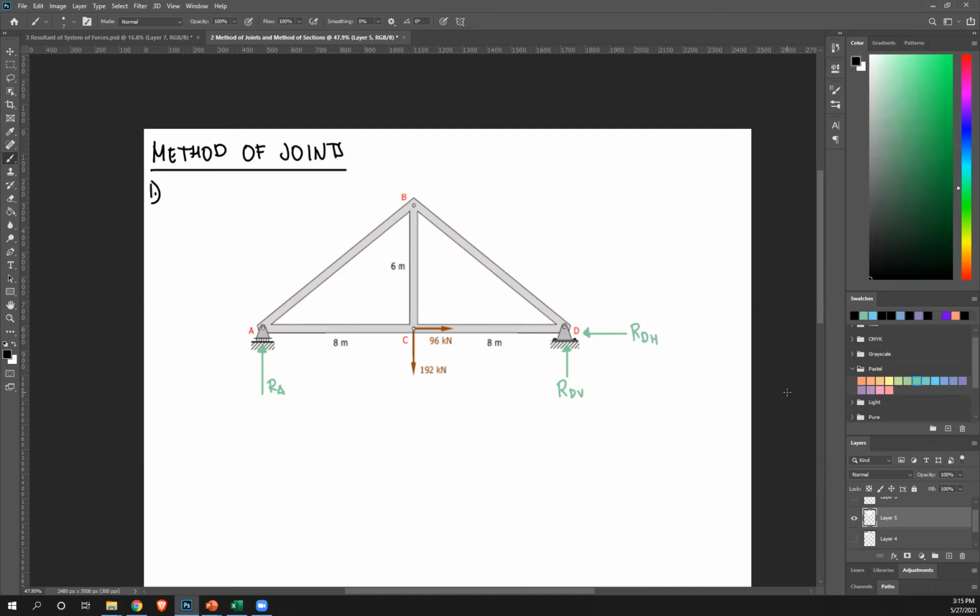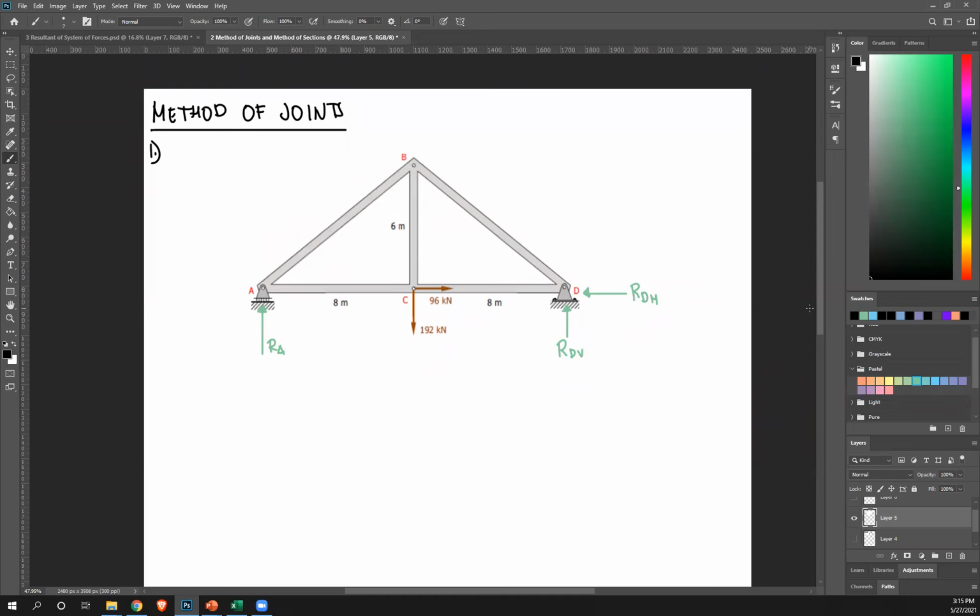Okay. Now that I've denoted my reactions, next step is to solve for them. So remember, one of the first things to do to solve for reactions is to use moment. Recall we have three equilibrium equations, right? Moment, Fx, and Fy. So usually for this, we start with moment. Next step, choose which point you'll take your moment on. So you can choose point B or point A, up to you, whichever you prefer. Let's try taking moment at point A.